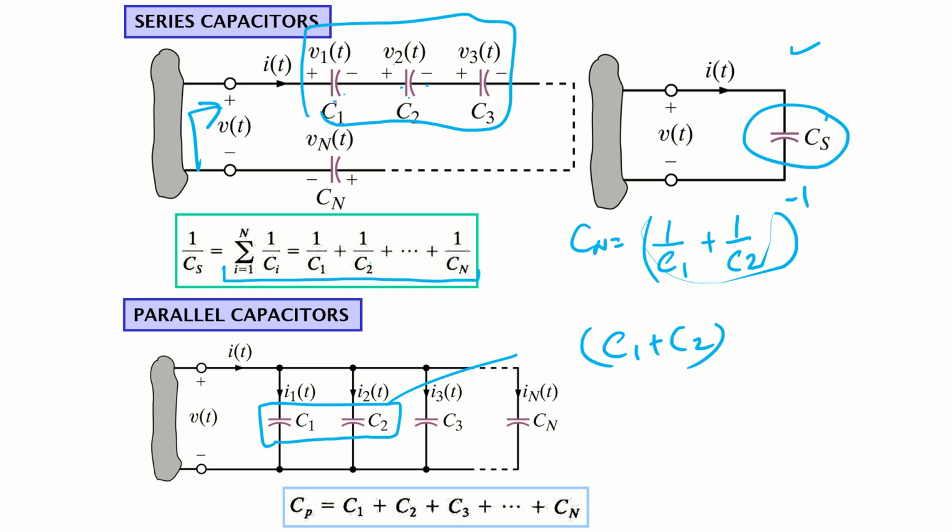So in short, series capacitors are calculated using the parallel resistor formula approach. For parallel capacitors, the net capacitance is calculated using the concept of series resistance of simple resistive circuits.